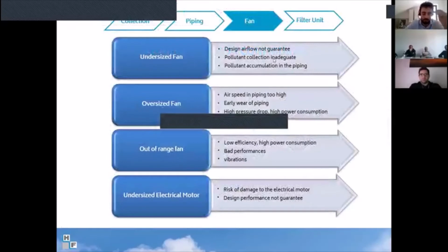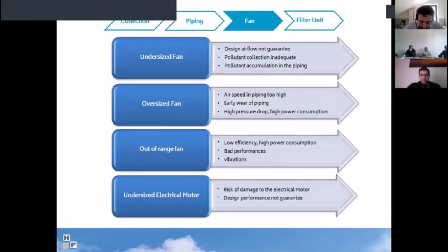If there isn't this range, we can't do anything. We can do it, we cannot do it, and in order to reach more performance, we not only have to install an inverter, so a variable speed drive, but we also have to change the motor, and sometimes a different motor, so a bigger motor, also needs a different impeller, because the connection is not always the same. Okay, if you don't have any other question, I can end the part related to the blower.